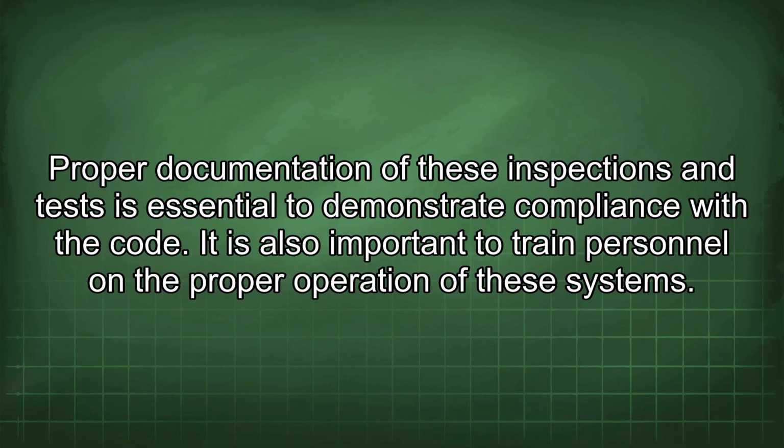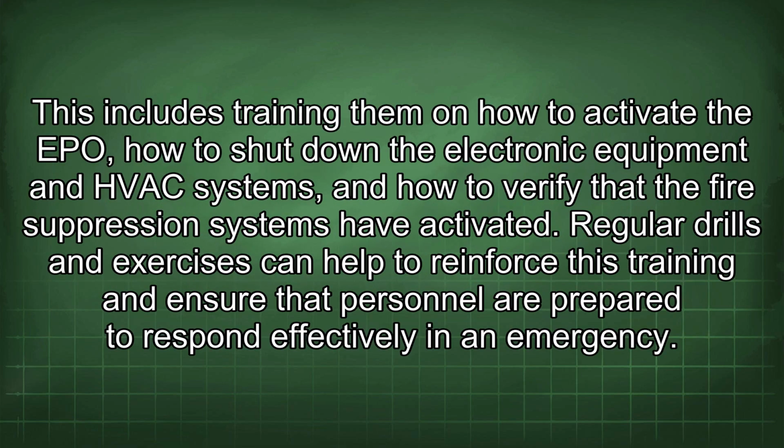It is also important to train personnel on the proper operation of these systems. This includes training them on how to activate the EPO, how to shut down the electronic equipment and HVAC systems, and how to verify that the fire suppression systems have activated. Regular drills and exercises can help to reinforce this training and ensure that personnel are prepared to respond effectively in an emergency.